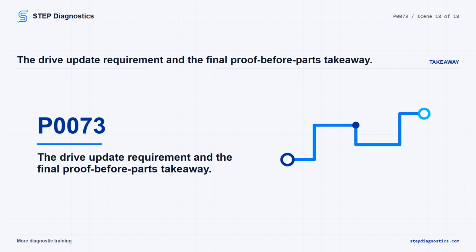After a wiring repair, a sensor replacement, or disconnecting the BCM connector during testing to correct an active fault, the ambient temperature signal may not update until the vehicle is driven for a minimum of 5 minutes above 15 mph. After that, verify the repair and confirm P0073 stays gone.